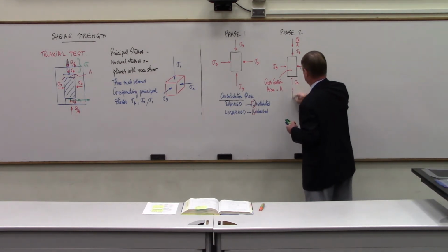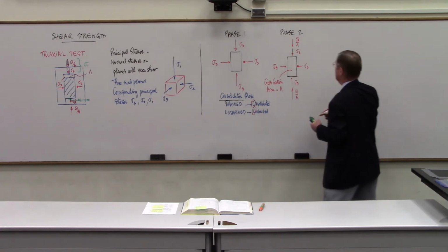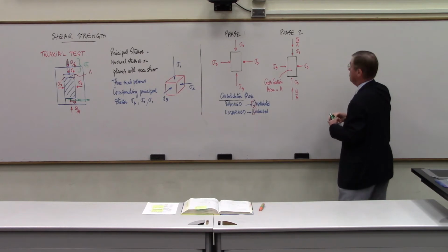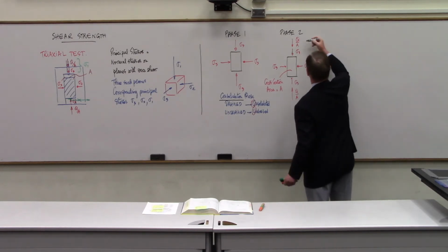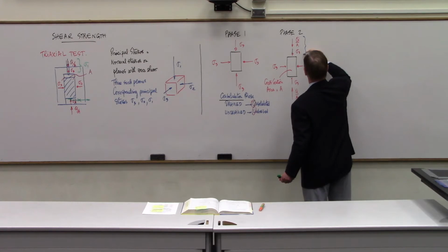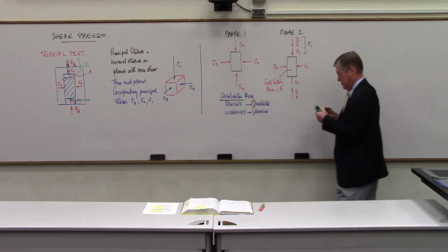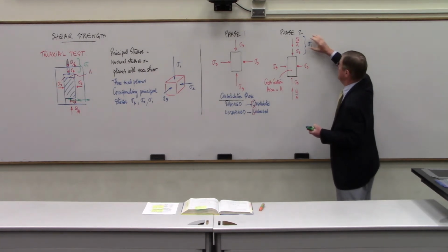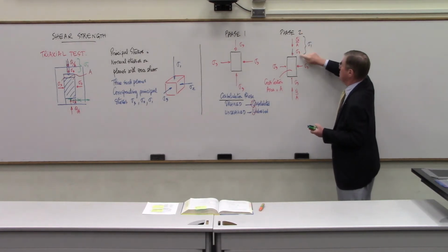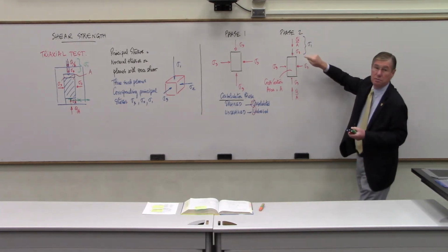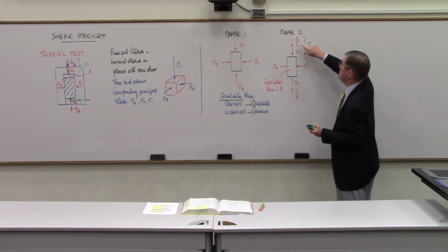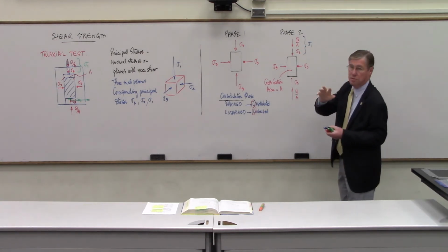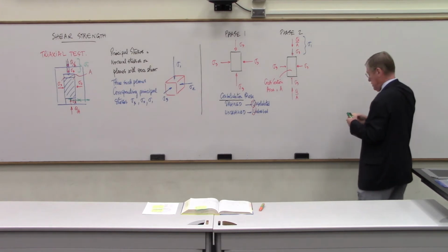So of course, action, reaction, we have the same thing at the bottom, Q over A, and then this altogether is going to form sigma 1. So be careful in some of the problems. I've seen some mistakes where people calculate sigma 1 equals Q over A. Don't forget sigma 3 because it's there. And so sigma 1 is sigma 3 plus Q over A. And we'll do some problem in a minute to exemplify this.